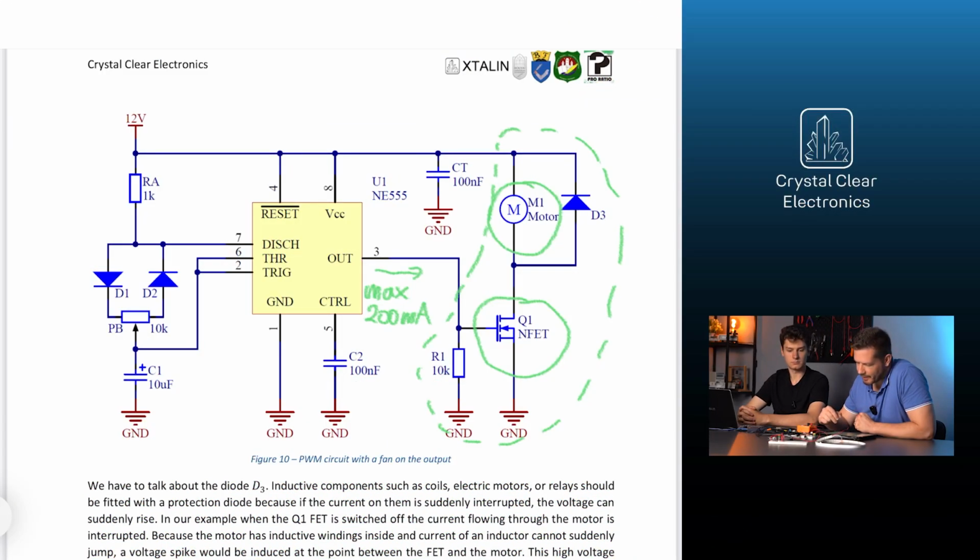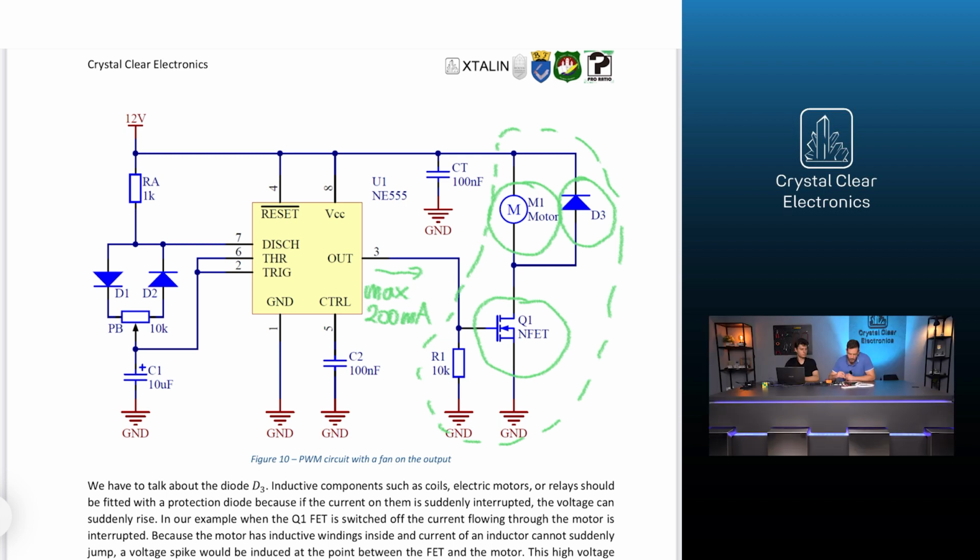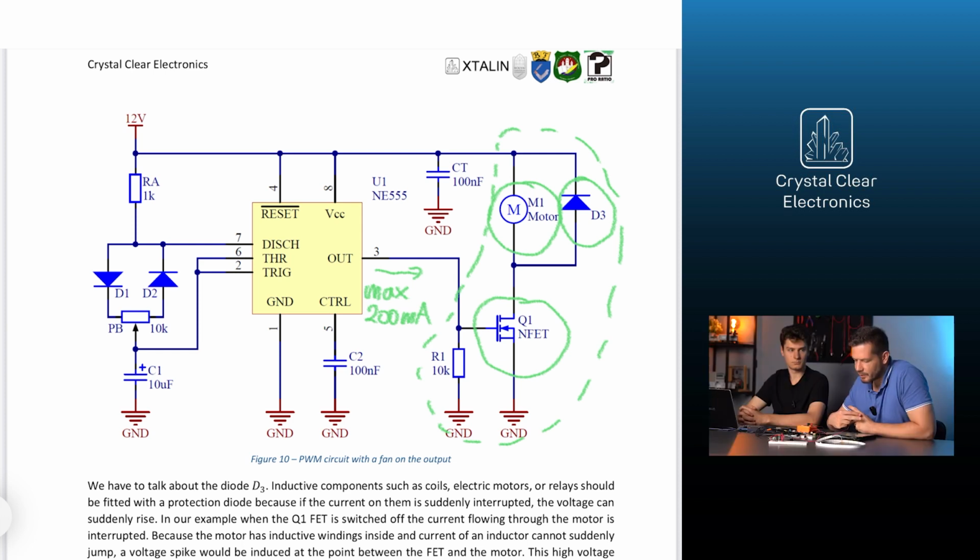On the other hand, if diode D3 is incorporated in the circuit, it will not allow the voltage at the MOSFET drain output to rise above the supply voltage, since the diode's cathode is connected to the supply voltage. This is because the diode will open as soon as its anode is at a higher potential than its cathode, so the current in the coil will continue to flow through it until the magnetic energy of the coil is consumed.